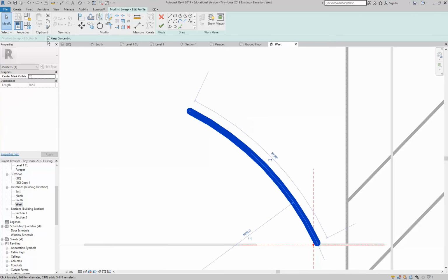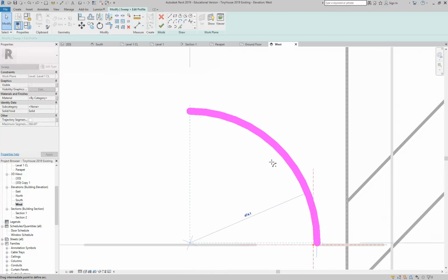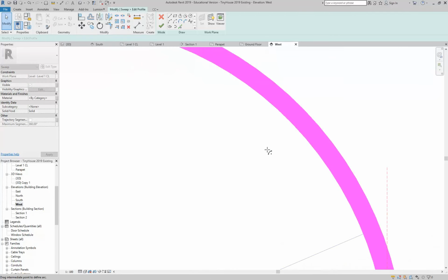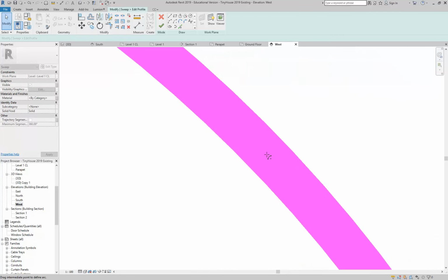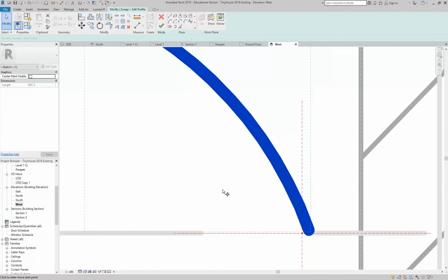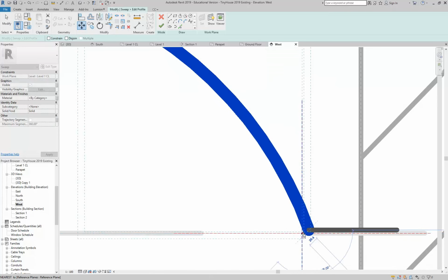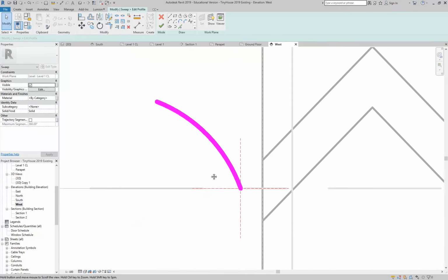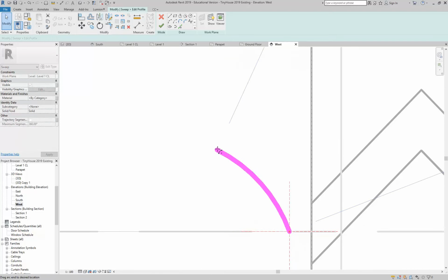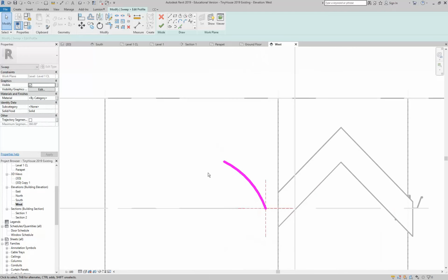So this sometimes gets turned on by default. You've got keep concentric. When that's off, then you can easily adjust the radius just to fine tune it, but it does keep snapping, so you've got to just avoid that. And it's a bit fiddly, but in the end you'll get it to work. So that looks about right, but you've got to fine tune it. It's a little bit of experimenting usually. So I've got that first curve, and then I might just shorten it a little bit because I know it's, just by eye, a bit too long.